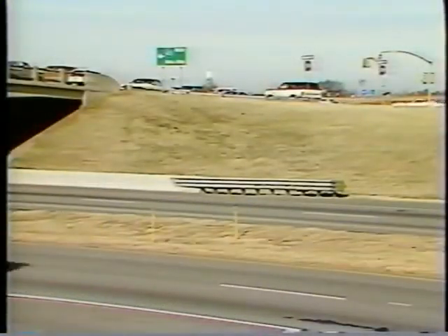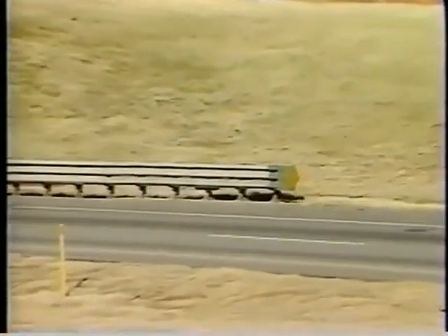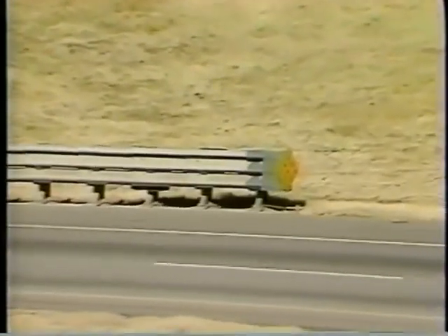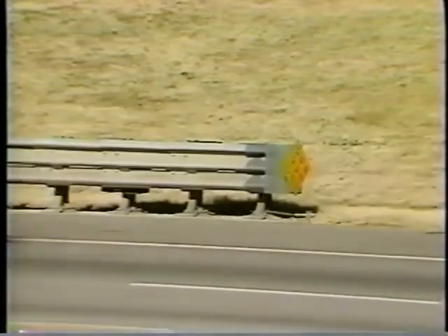When impacted in a head-on crash, the system's fender panels telescope in, the support posts shear, and the cable of the system activates to redirect the car into its normal travel lane or slows and stops it. The sand containers on the first 3 posts of the system assist in the deceleration of the vehicle. Installation of the Sentry is relatively simple, as the manufacturer's installation instructions are complete and well illustrated. When combined with a standard work order and work plan, sufficient information on system installation is available to make putting the system into service an easy task.